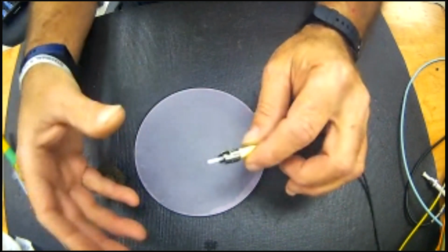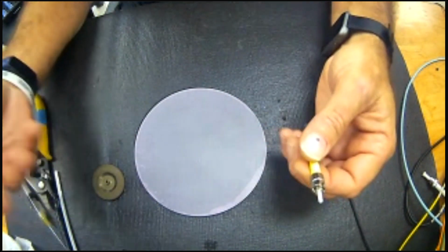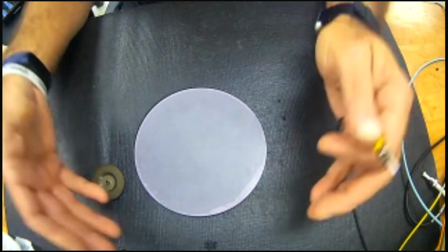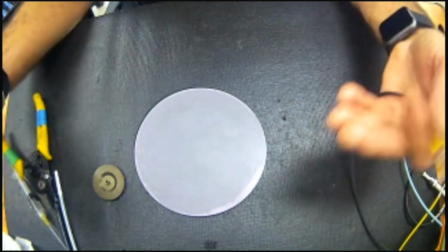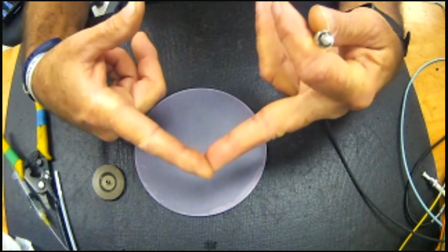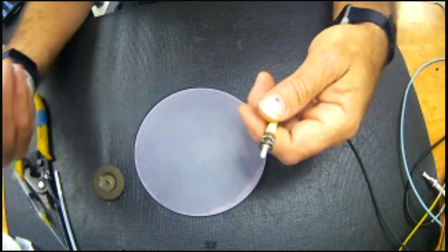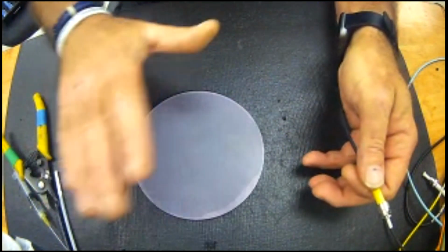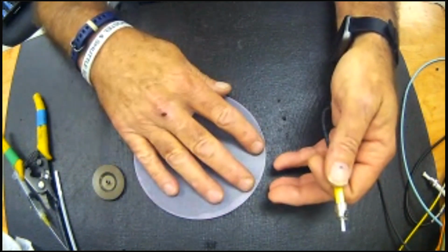Ideally, you would want UPC machine polishing, but that is when we're talking 4 to 6, 8, 12, 24 connectors in line. Most field connections, there's only 2, 3 jumpers involved in it before it's reclocked or it's device to device. Most of your media converters, most of your hookups on your I/O of your trucks, or your I/O at the truck dock, or the output at your portable cases. In this case, like I said, diamond film is my preference. You can also get this in aluminum oxide, which is an inexpensive film.